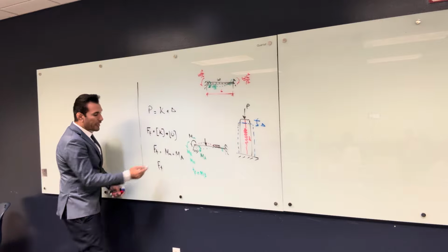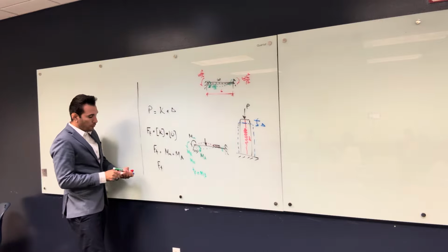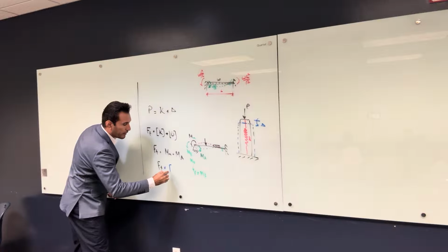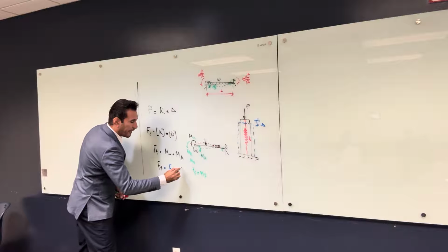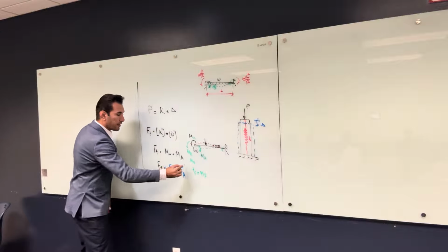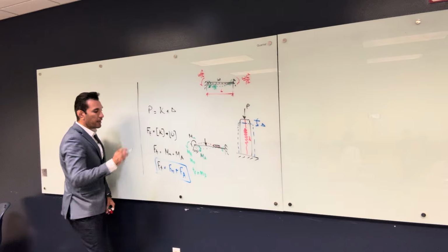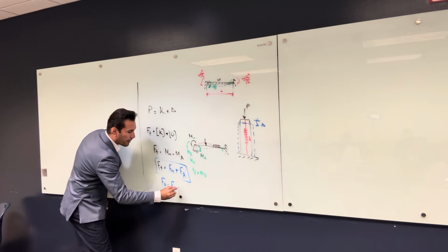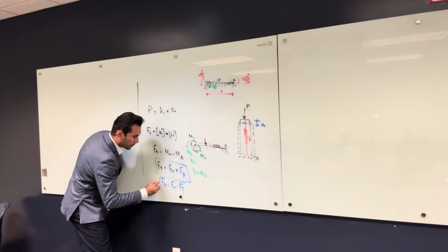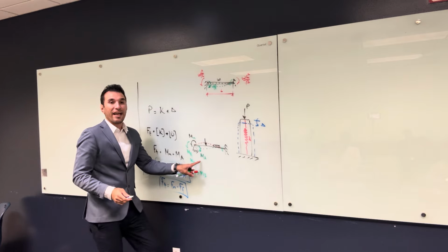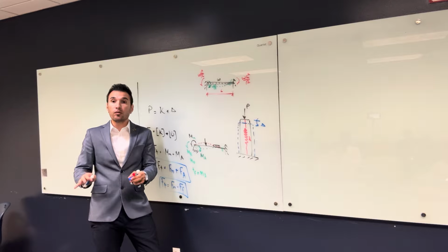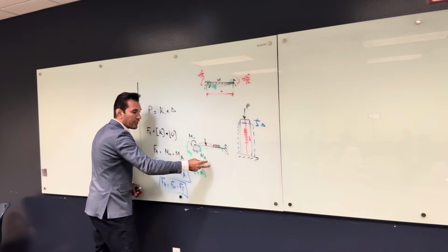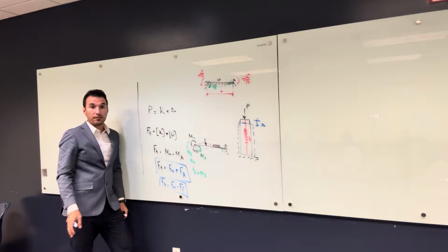All right, so we can write F total is equal to, I'm gonna write it in a general way, the F nodal forces plus the F action. That is a general rule. But we usually write it as F total is equal to Fn minus F fixed end forces. Rather than dealing with action, because when we solve a structure, we don't solve for actions, we solve for reactions. So we are gonna move the action to be a reaction with a negative sign.